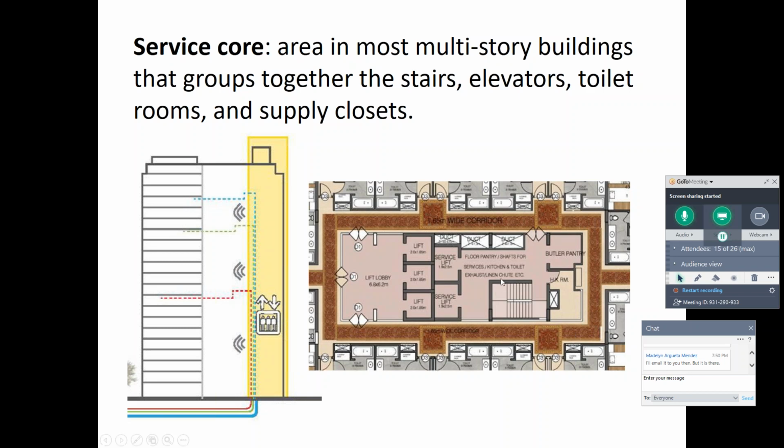Here we're showing it at the center, and it's mostly what we have now, especially in cities, right? It provides for the smallest footprint. So you put all of your workable, livable space on the exterior, put all your elevators at the center, as well as maybe your housekeeping and localized bathrooms. And that way, everything on the exterior is consistent. So most consistent, smallest footprint. But then you might have another designer who believes that all the living should be at the center, and then you want to vary those areas at the four corners.